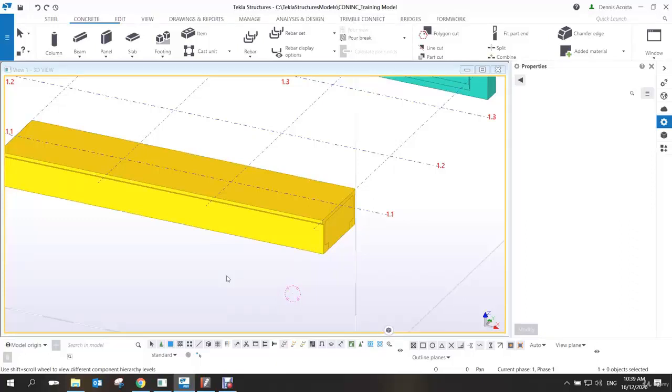Okay? Because assembly is the one that you produce in shop. So let's say, for example, this one is a wall. The wall consists of opening, reinforcement, embeds, lifting anchor. So this whole assembly will go to the shop, and then you will form that in your shop floor. But the component, I can have the component for opening only. I can have the component for lifting only. And I can have one for reinforcement only. If I put, let's say, the 5 different components, I can form one assembly.